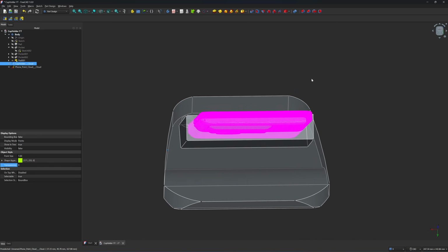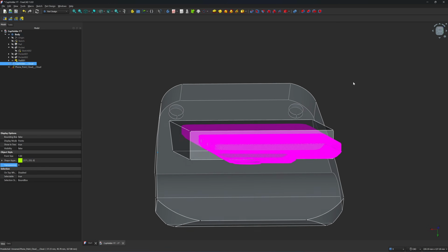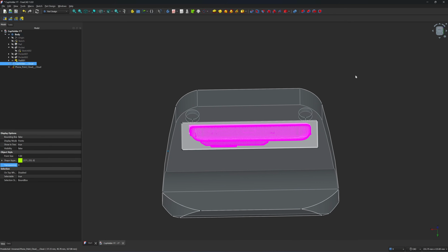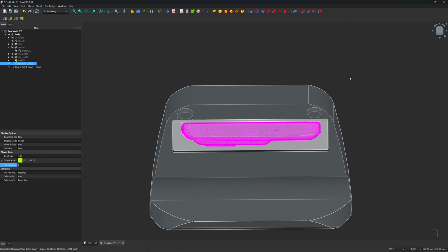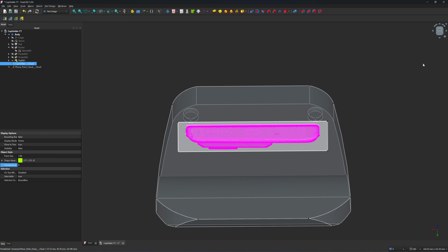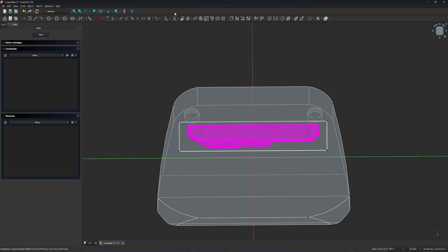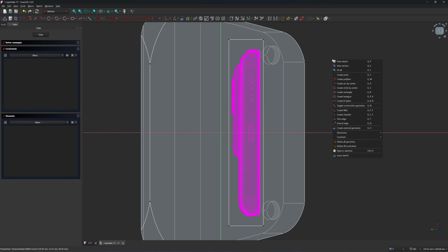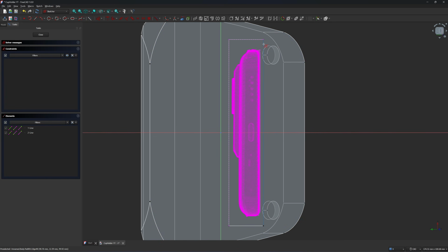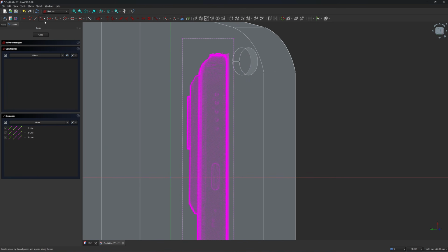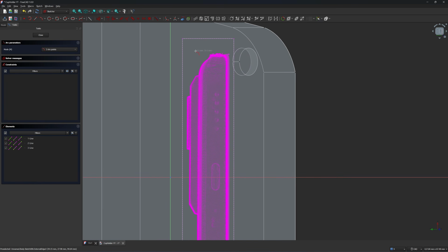Now after I turn off the cup holder, it's very smooth with the orbit, so you should import just enough point cloud, not import too many. I'm going to click here on this plane, create a new sketch. And then I'm going to cut the profiles. Before that, I need to project this 3 dimension, and then I'm going to make a profiles.